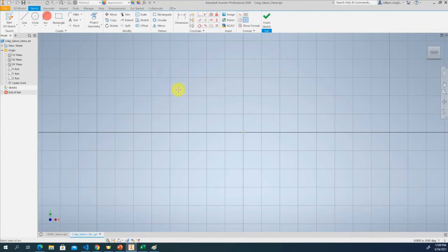So the way I found the easiest way to do this, I'm going to create an arc. My arc, I want my line to run vertical. So I'm going to give this first off this distance. I'm going to make this 6 inches, for instance. And then I'm going to press tab. I'm going to set my degrees to 90 because I want this to be perfectly up and down. And then I'm going to hit tab again. Make sure you hit the tab, that way it locks in both of these numbers that we just put in, and we can press enter.